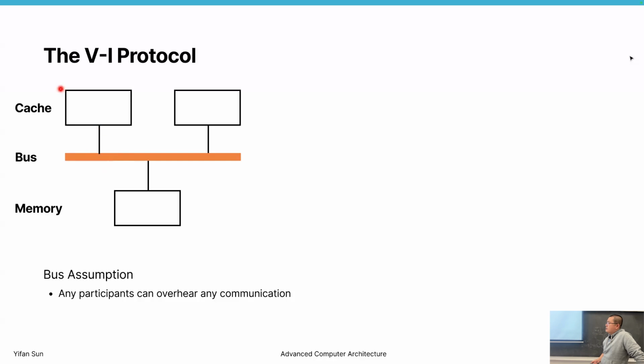So we're saying this cache unit and this cache unit can share this bus. When they share a bus, there must be an arbiter. The arbiter decides who can use the bus in a cycle. They first communicate with the arbiter, saying, I have something to send, and the arbiter says, you send it this cycle.